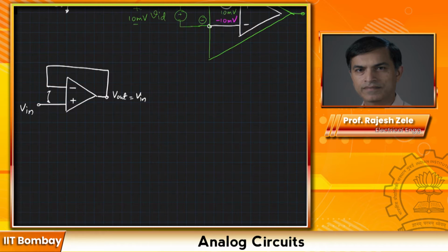So what we would do is erase only this portion right here. And then, as I said, we would introduce offset voltage in the non-feedback terminal. So this would be plus minus VOS. You can immediately convince yourself the input voltage over here, using Kirchhoff's voltage law, will be V in minus VOS. Hence, the output voltage will also be V in minus VOS.